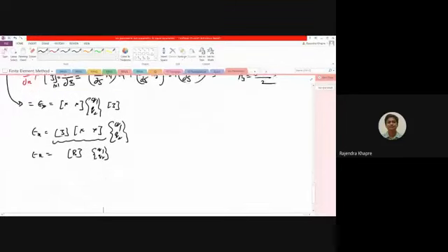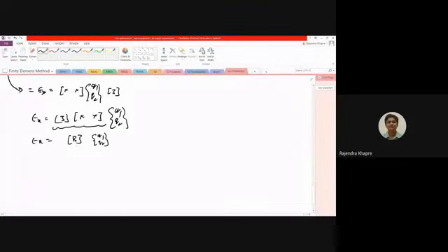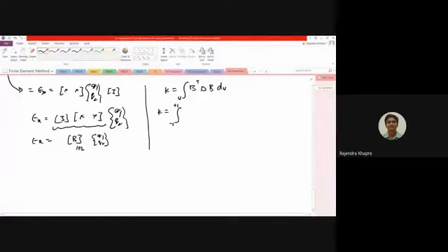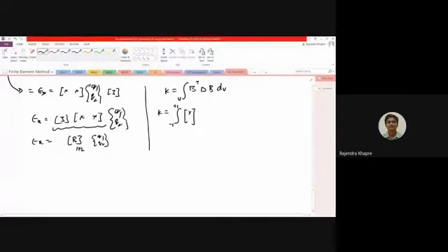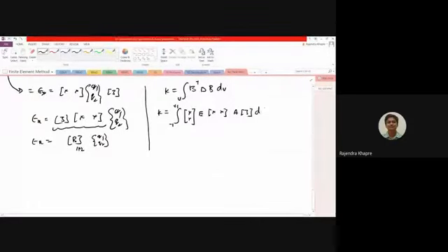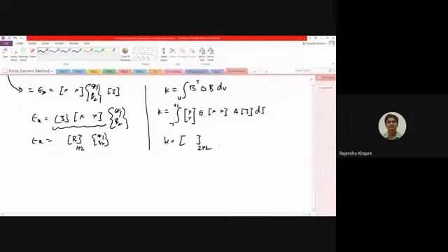So basically what I'm trying to say over here is your B matrix will have one row and two columns. If you go for the derivation of the K, K is the integration over the volume of B transpose into D into B over dV. The same expression can now be written from -1 to +1. Your B transpose will have only two components, your D is nothing but your E, and dV can be written as A into the determinant of J into d xi. As a result of this, you will get a K of size 2 by 2.